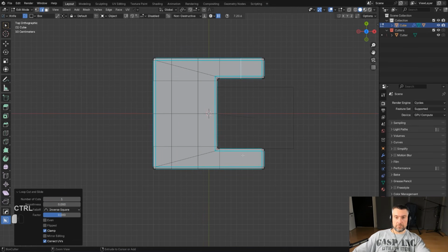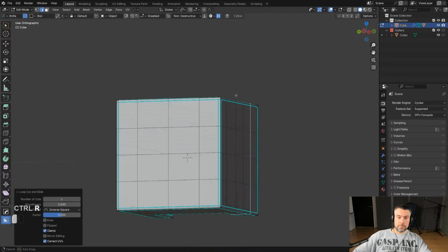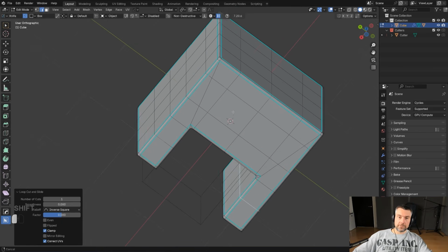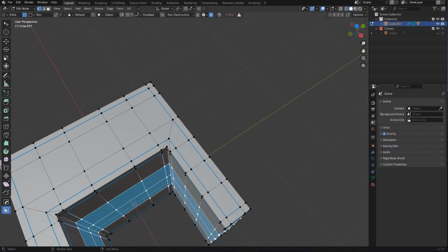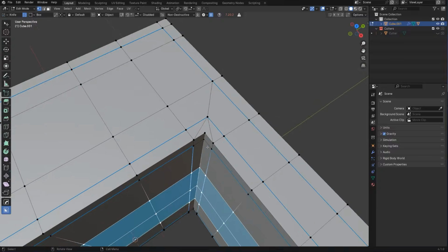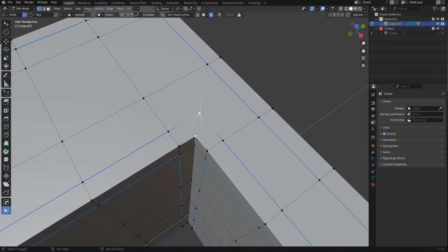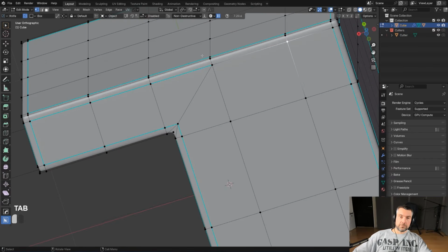Okay, you can run 2 loops in here, and this is going to be a much more balanced mesh in terms of Sub-D. Obviously we don't need to run it in here, we can run it in here, and we can combine these two together. And then last but not least, you need to fix this issue here. So we need to solve this corner by simply removing these 2 edges, and everything is peachy, and that looks clean to me.